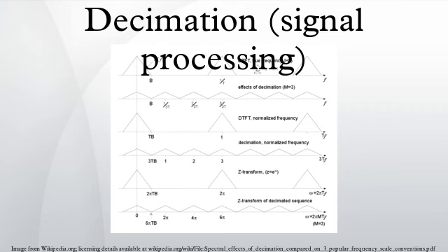The lower graph is the new distribution that results when x(t) is sampled 3 times slower, or when the original sample sequence is decimated by a factor of M equals 3. In all three cases, the condition that ensures the copies of X(f) don't overlap each other is the same, where T is the interval between samples, 1/T is the sample rate, and 1/2T is the Nyquist frequency. The anti-aliasing filter that can ensure the condition is met has a cutoff frequency less than 1/M times the Nyquist frequency.